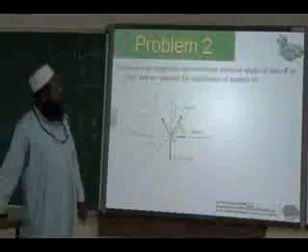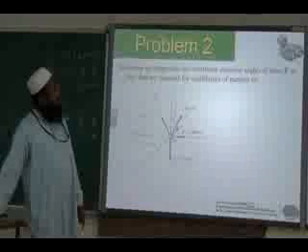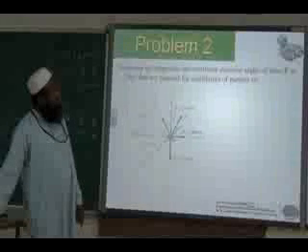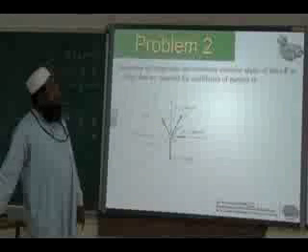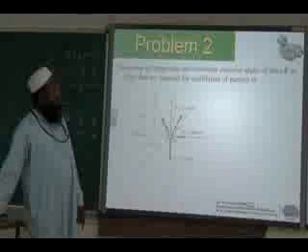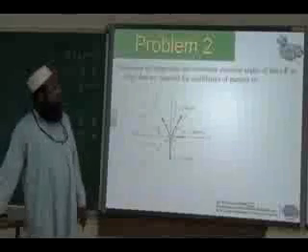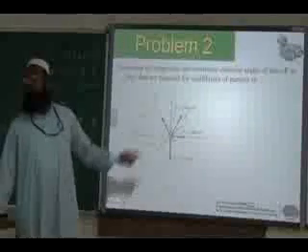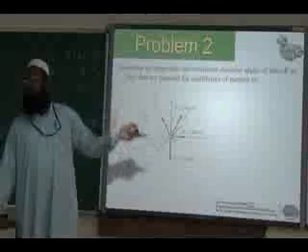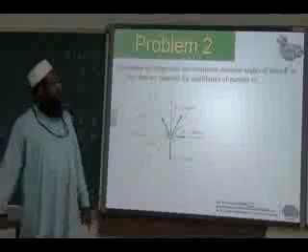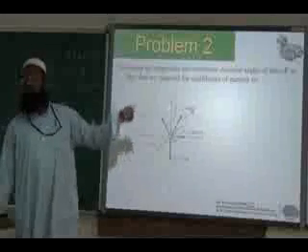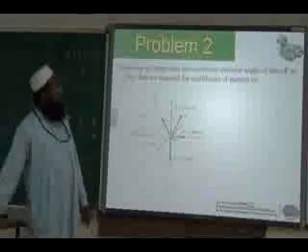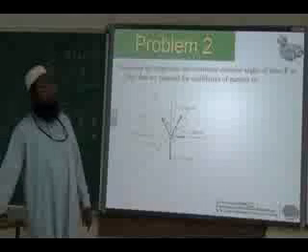Whereas F3 is in this place, so we have to consider the coordinates of the force acting along OB. We have to find the position vector along OB, then find the unit vector, and the magnitude of the force, 700, times the unit vector will be the Cartesian form of the force along OB.